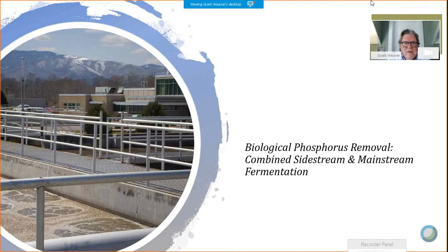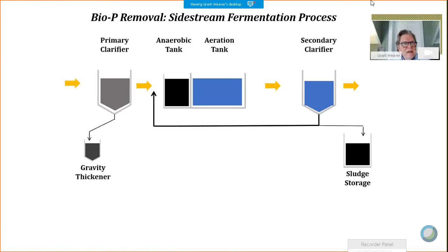Even more sophisticated way, and this is the Missoula, Montana facility, where it's probably barely colder there than in places in Tennessee today, combines a side stream and mainstream. So let me get into that and explain that. By side stream, we're creating the volatile fatty acids in one place. Now, this type of facility, sometimes they'll measure how many VFAs are produced in this.